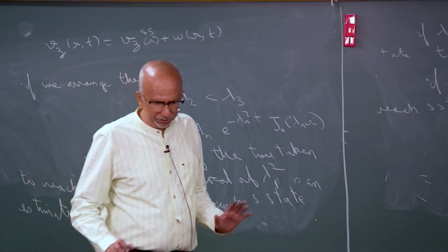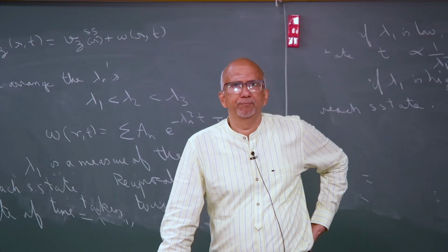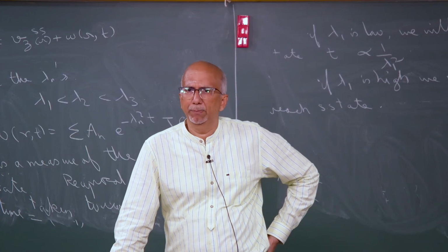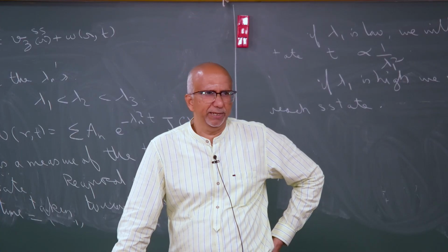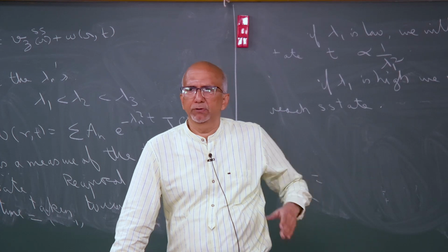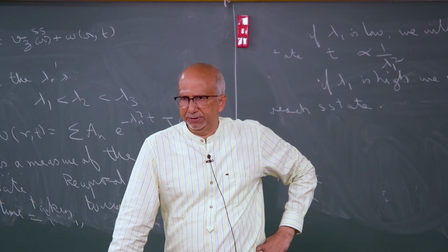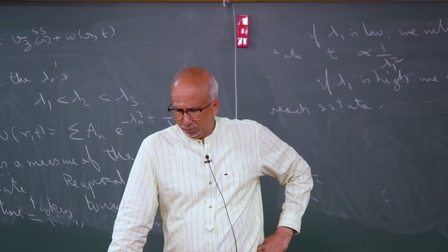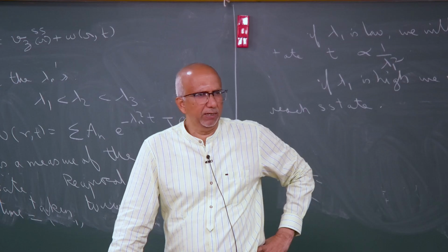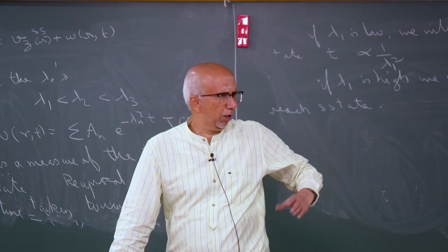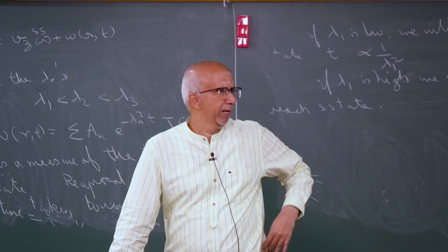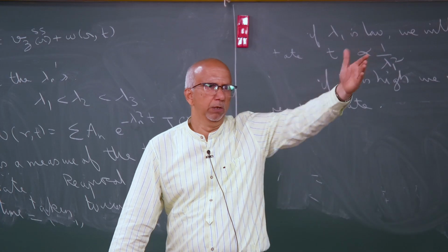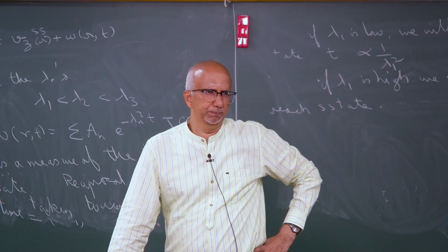Okay. So, this is basically a transient problem which we have solved, and because it is linear, we have been able to get some insight about the time taken for it to reach the steady state. Okay. So, what we have done is a fluid mechanical problem where the pressure drop was imposed and we looked at the time taken for the fluid to go from rest to some final steady state value.